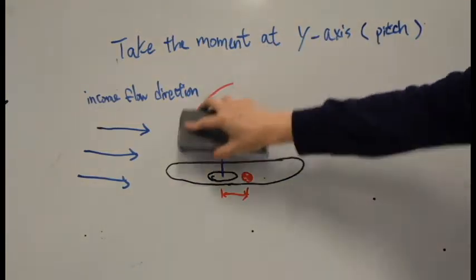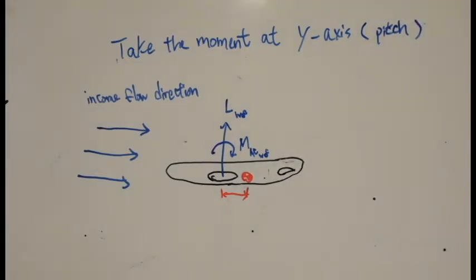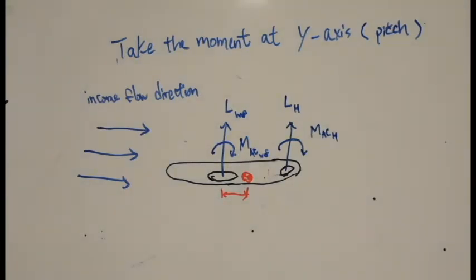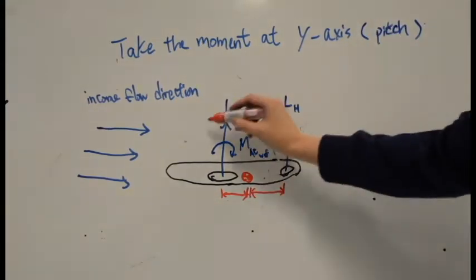But if there is a tail part at the aft of the aircraft, a lift force LH, for horizontal stabilizer, will be produced, and hence an opposite pitching moment will be produced. Also, there will still be a moment due to the uneven lift distribution on the tail wing surface, but as the surface of the tail wing is too small, the twist could be ignored.